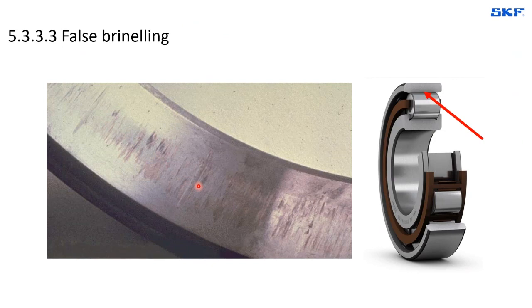So we can conclude from this initial assessment that the vibrations that were creating this false brinelling damage were happening when the bearing was standing still, but also when it was operating. So there are many more irregular marks. And one of the things that helps us to distinguish this is the discoloration. They tend to be reddish and sometimes shiny at the depression of the wear that is being generated.